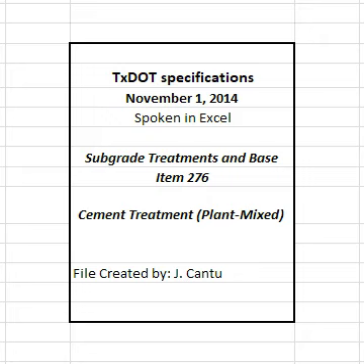Strength requirements. Class N, 7-day unconfined compressive strength, minimum PSI. Class L has a 7-day unconfined compressive strength of 500 PSI. Class M has a 7-day unconfined compressive strength of 300 PSI. Class N has a 7-day unconfined compressive strength as shown on the plans.